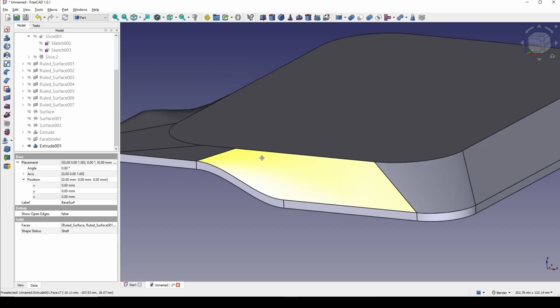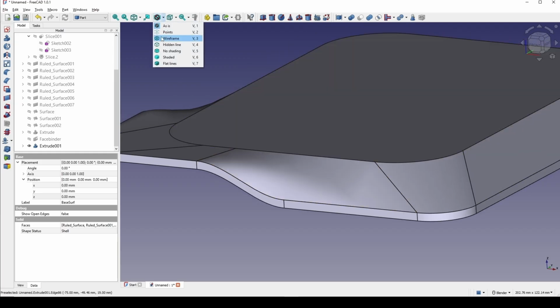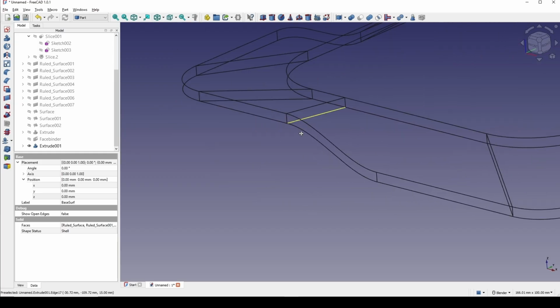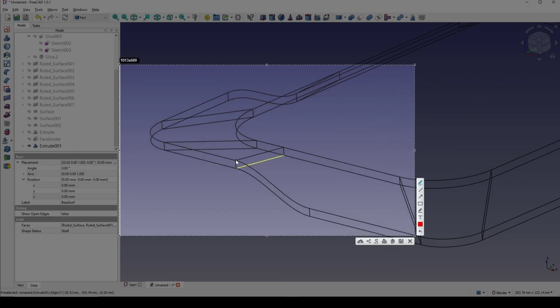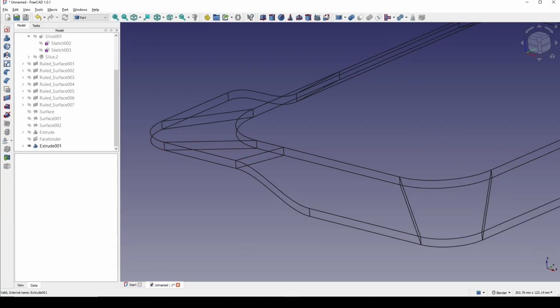But if I go inside the wireframe, you can see in between we have the extrusion just generate many faces in between. Later, if you want to export this to a different program for rendering, you have a shading problem.